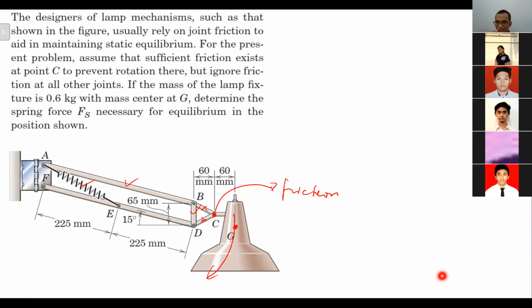How can we handle this? The easiest way, as always, is to solve for the multi-force member: create a free body diagram for the multi-force member, and replace the two-force members with an extra force. So for this, the easiest way to solve it is to solve for FED.